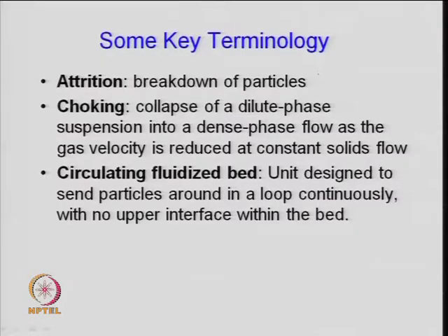When you reduce the flow, all the particles will come to one point, and that is what you call the dilute phase going down. It has now become a dense phase, where more particles or clusters of particles are located at one point. We have a kind of dilute phase where the gas can pass through, and there is good contact between the gas and the solid catalyst, and the product forms. So, dense phase and dilute phase, these will be there.